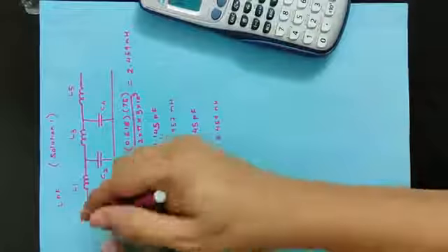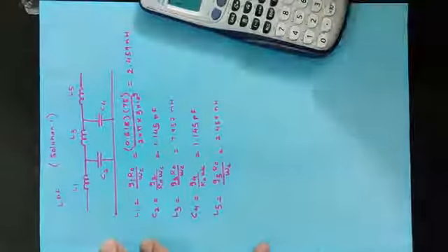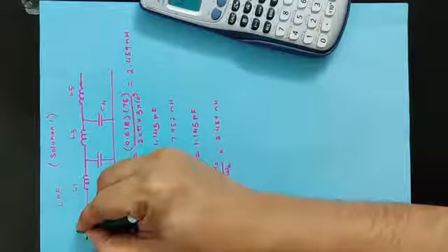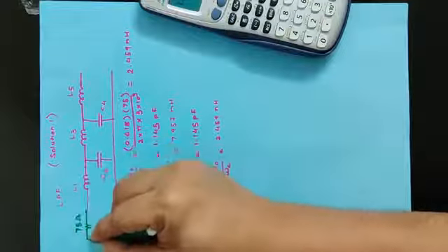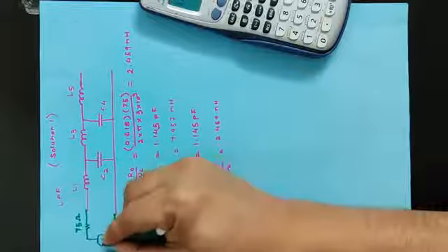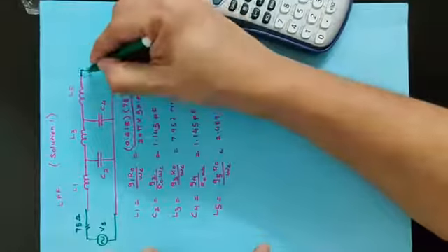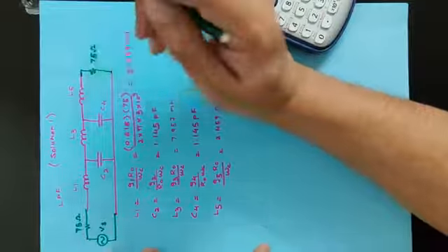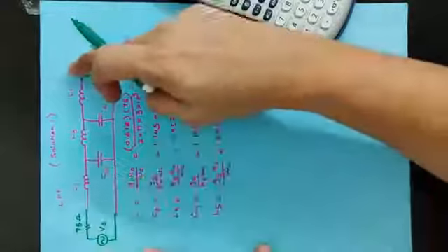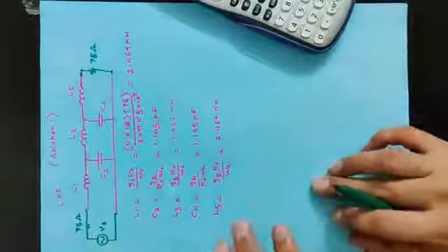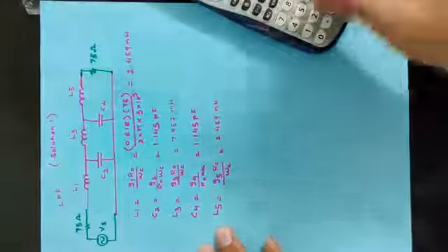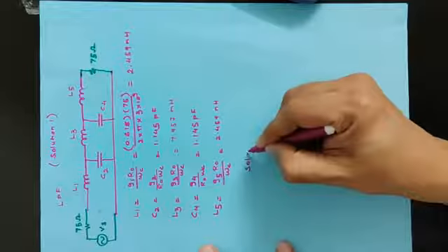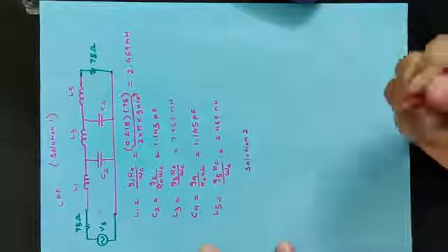So we have calculated the values, and now we'll complete the circuit diagram. Here you will have R0 at 75 ohm. You will have the source over here, and here you will have the load resistance 75 ohm. So this is my port 1 and this is my port 2, and the elements are connected in this manner in solution 1.